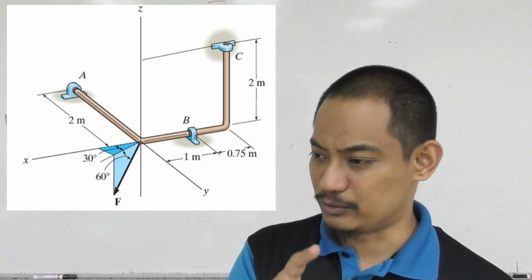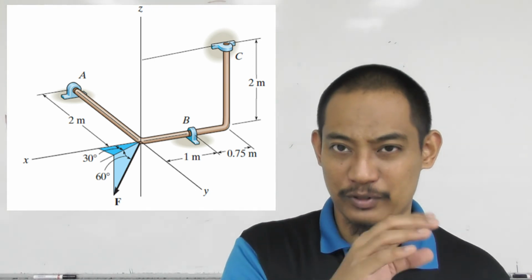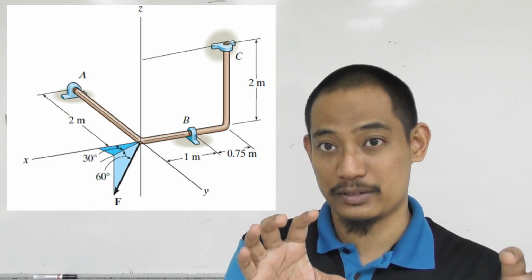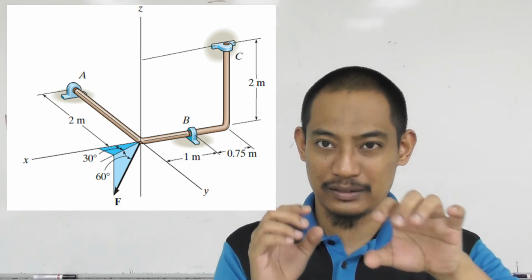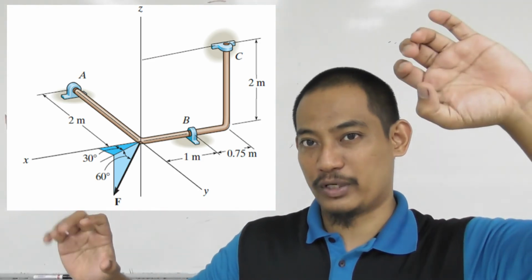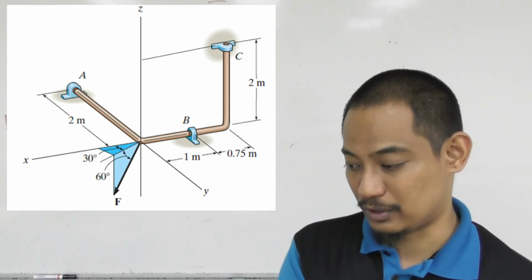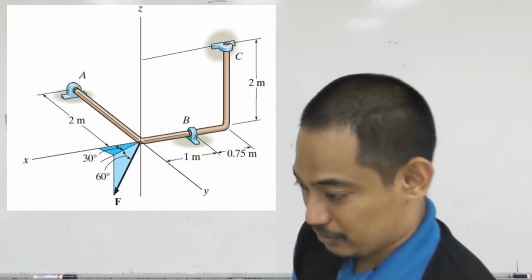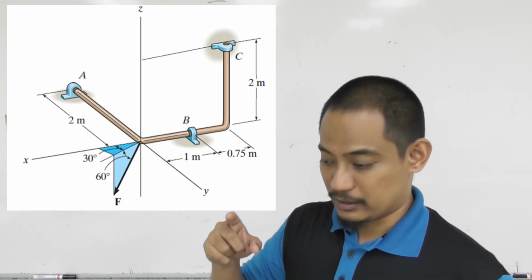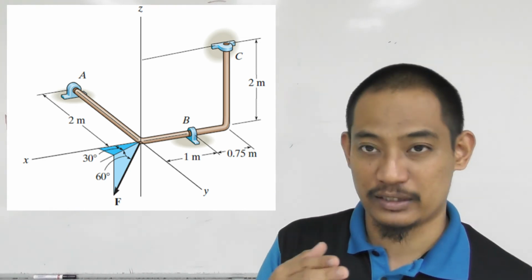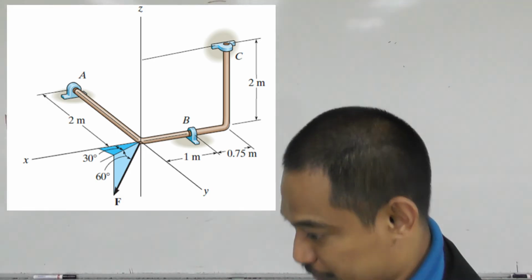And if you do not understand that, you can ask in the comments or in the class, or go back to my example of what is happening when we say it's properly aligned, right? Where the bearing actually can resist the moment, but it is not triggered because the bearing elsewhere already prevents that movement, so it will never allow for that rotation anyway, right? So that moment is equal to 0. So that's basically it. Alright, so we'll go straight and I will draw the free body diagram so that we can answer this question, because the question is to find the support reactions at all the supports, meaning at A, at B and at C. Alright, so we'll draw the free body diagram.